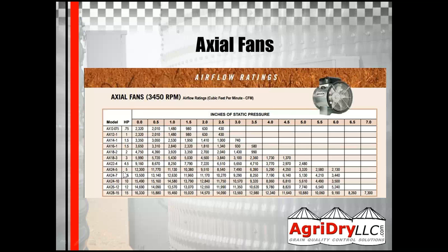But on any type of situation, we don't want to have too high a static pressure because, as you look on these charts, the airflow goes down tremendously the more static pressure. Like I said, that static pressure is calculated off the grain depth and the horsepower. So that's when it comes to sizing your fans properly. You don't want to have too much fan, because if you have too much fan, then you have too much static pressure, and you think just because you have more fans, more horsepower, you have more airflow. Well, that's a lot of times not the case.